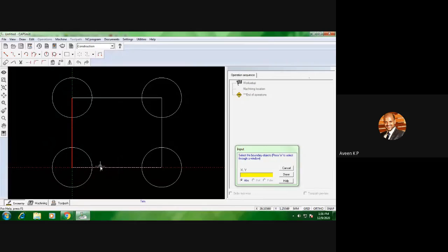So you just select all. See, this particular area has been selected. I will click done and select the object on the side to be trimmed. So which is not required, you just trim it off. See, for me, this particular edge is required, whereas this is not required, this is not required, this is not required. So which is not required, you just trim it, so it's done.